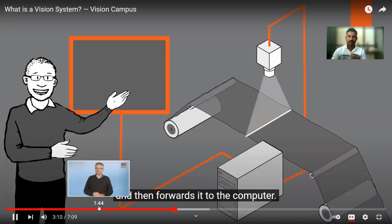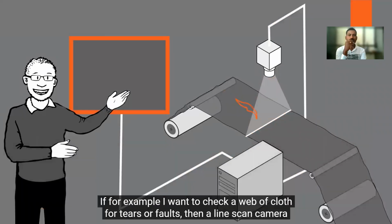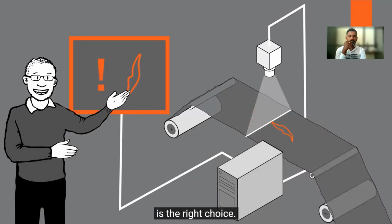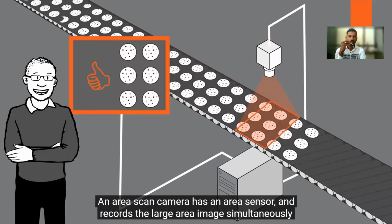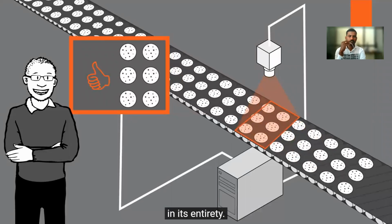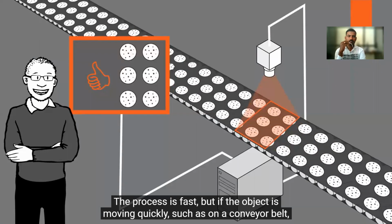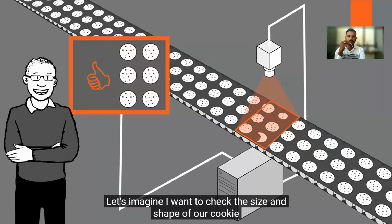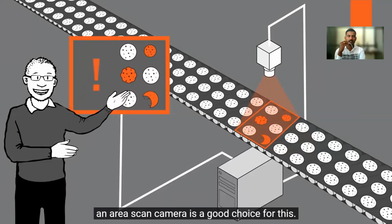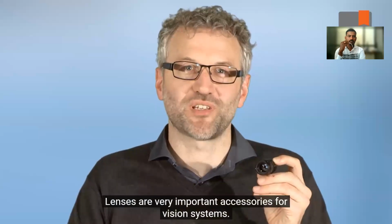It works well when a conveyor belt is used to move the objects to be inspected. If, for example, I want to check a web of cloth for tears or faults, then a line scan camera is the right choice. An area scan camera has an area sensor and records the large area image simultaneously in its entirety. The process is fast, but if the object is moving quickly, such as on a conveyor belt, there can be motion blur. Let's imagine I want to check the size and shape of our cookie. An area scan camera is a good choice for this. Lenses are very important accessories for vision systems.